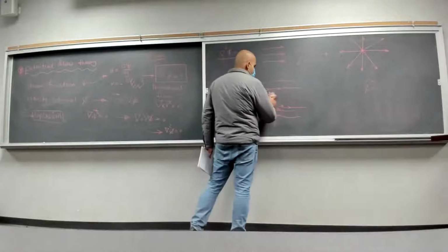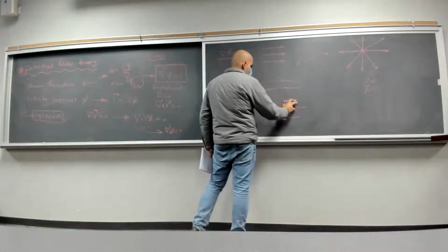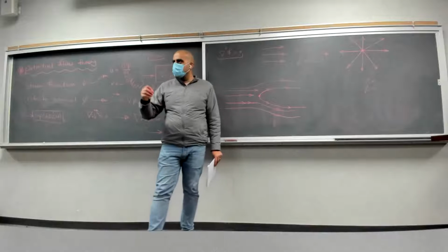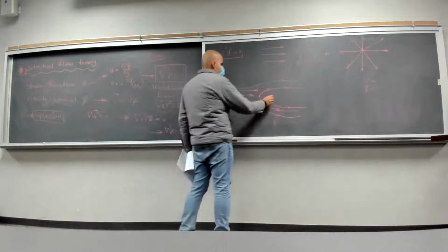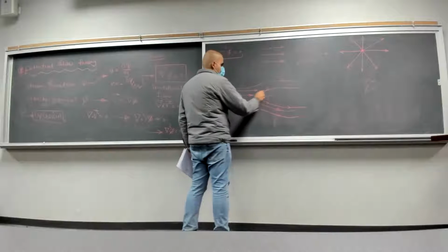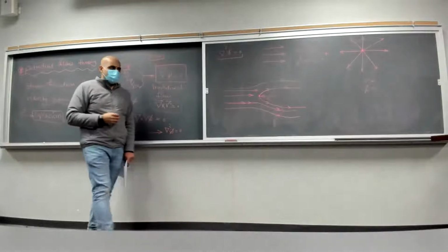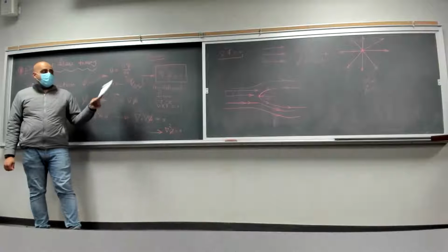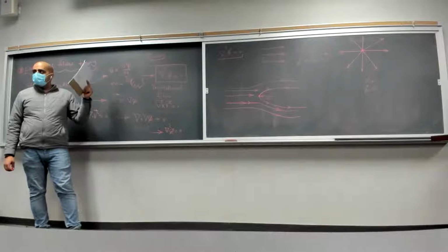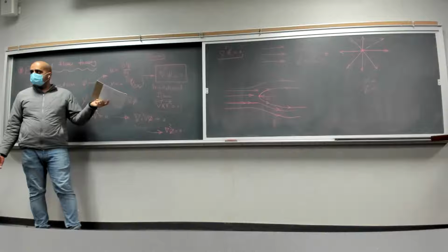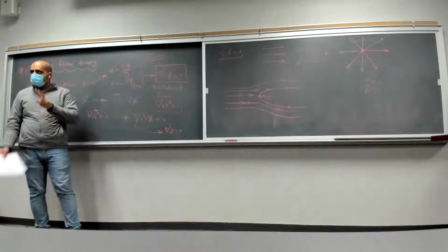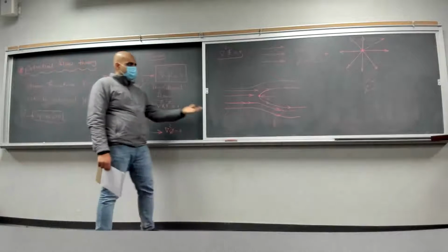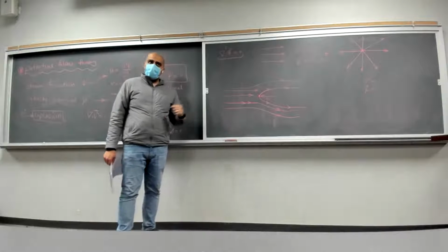If we remove the inner parts by just adding a condition, r is always bigger than this radius, we essentially remove the source flow parts. What does this look like? This looks like flow over an airfoil, right? So we're essentially using two simpler flows. We are going to create a more complex flow.